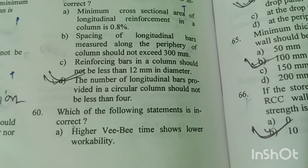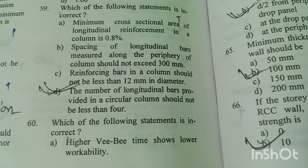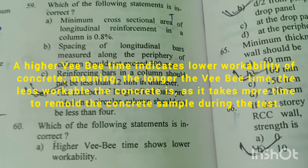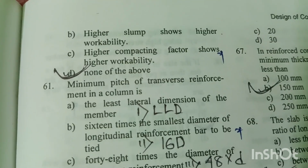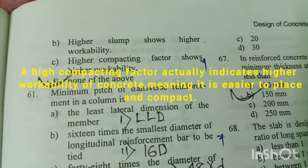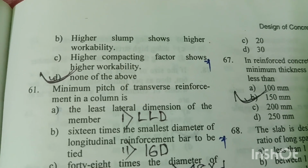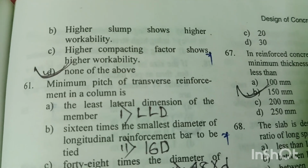Question number 60. Which of the following statements is incorrect? Statement A. Higher VB time shows lower workability. Right. Statement B. Higher slump shows higher workability. Right. Statement C. Higher compacting factor shows higher workability. Right. So option D is the right answer. None of the above statements are incorrect.